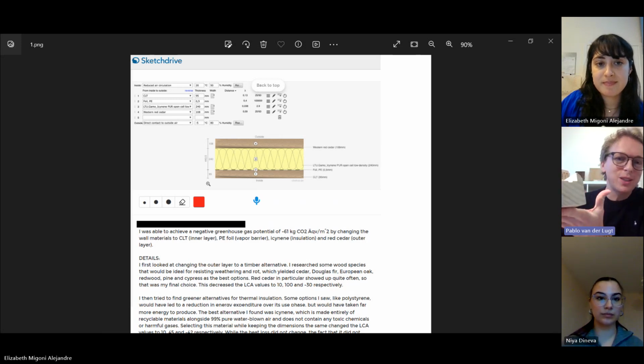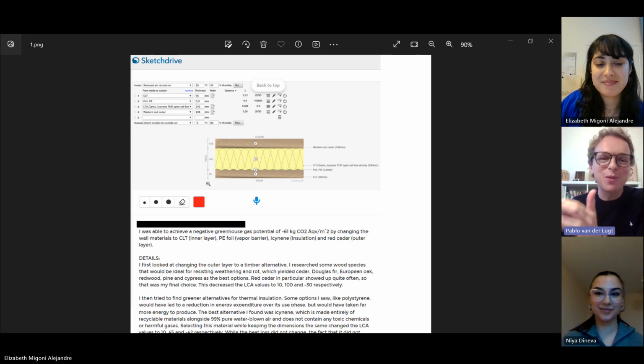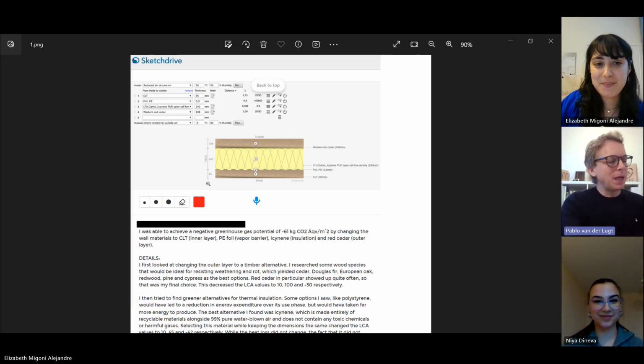Another example is acetylated wood, which goes through a vinegar treatment. This is a piece. Well, you can smell it. I can smell a little bit of vinegar in here, but this makes the timber totally rot resistant, gives a guarantee of 50 years outside. So it shows that there are very good examples also on the outside of a building for the cladding. That can be timber. It doesn't have to be timber, but there are very weather resistant examples.